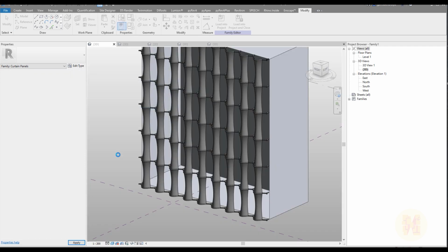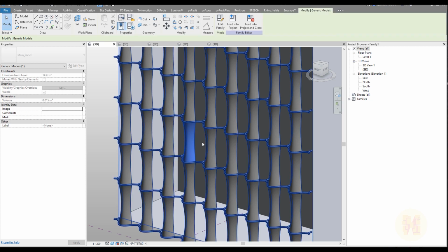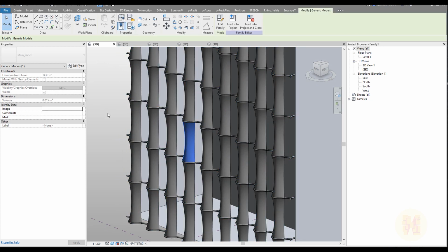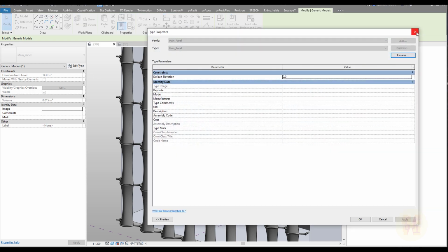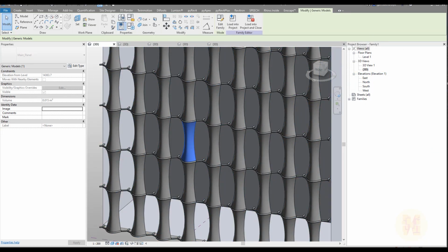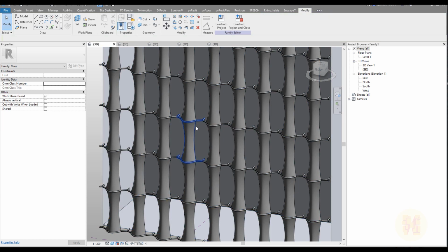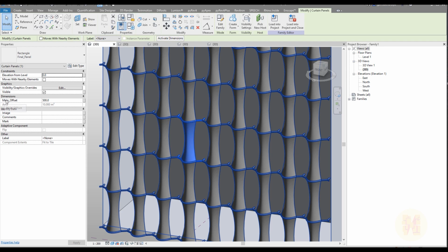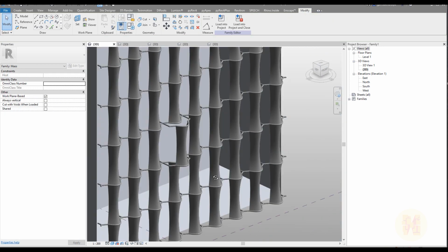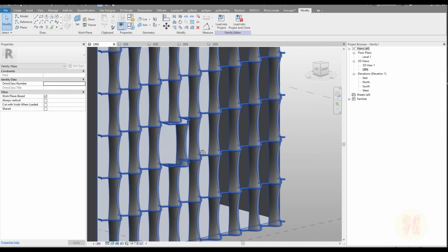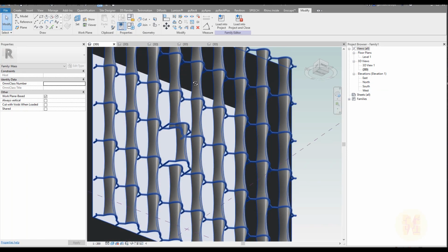Override parameters, and now I can select one panel, as you can see here, for example, and I am able to change the parameter offset. Where is the parameter offset? Actually it's here, but you should use the tab key. Be careful because we want to select the panel, not just the surface, like this. Here, now I'm selecting the panel. Once you select the panel, you will see these parameters here, 500 millimeters. I will change it to 1500 millimeters, and what we will get, as you can see now, is it's going to the offset. This is only one way we can make our panels parametrical.